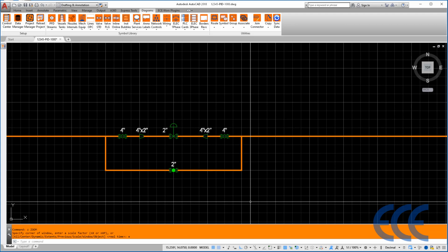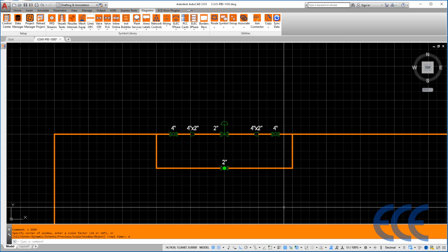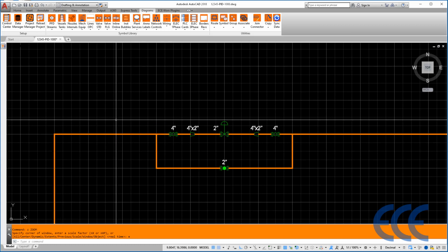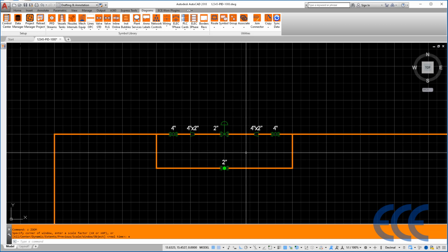and go ahead and outfit this control valve with a pressure loop. So I'm going to add a pressure transmitter. Then I'm going to add a couple bubbles to the valve. First, I'm going to start out with a current to pneumatic converter, add an isolation solenoid to that, and then connect those instruments to some PLC inputs and outputs, ultimately going to a shared display. So that should give me quite a bit of content to show you here.